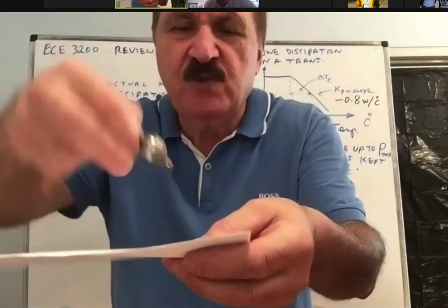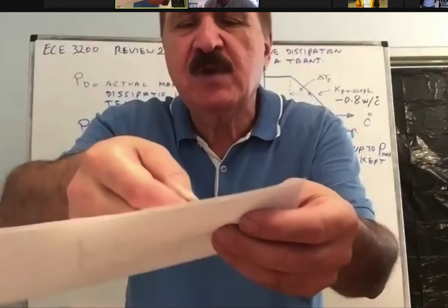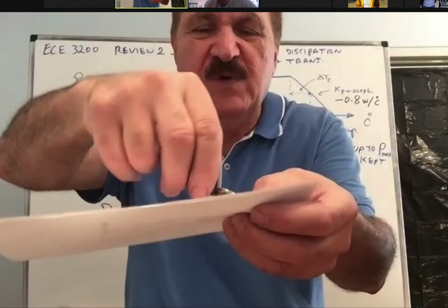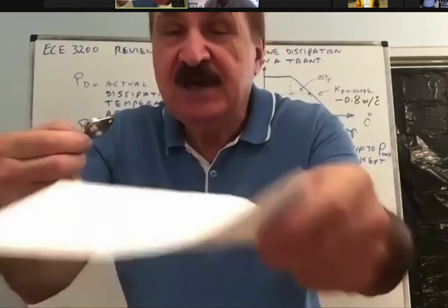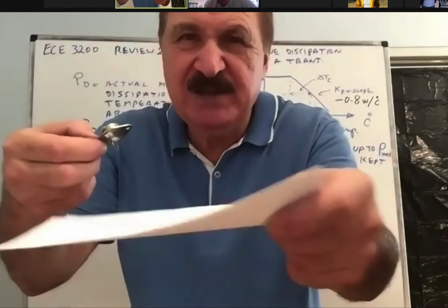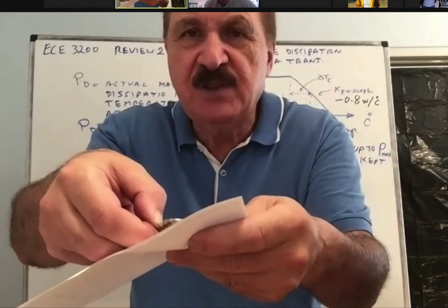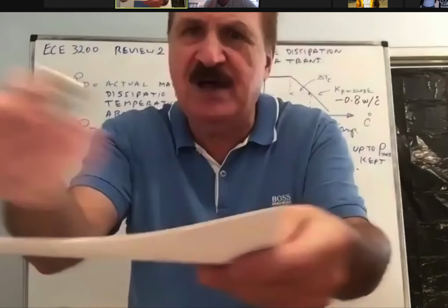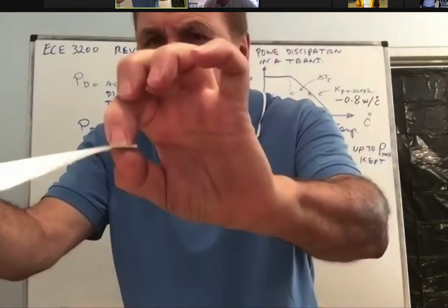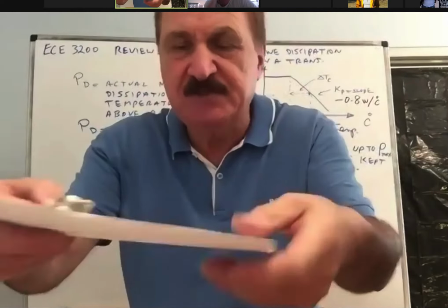We have to drill holes so that the pins will go through, and then we have to isolate the body from that plate, because the plate is an electrical conductor. This is the collector. If you install it there, the whole body becomes a collector, which sometimes we would love to do. We put a screw on the top of that metal and it will become the collector lead.